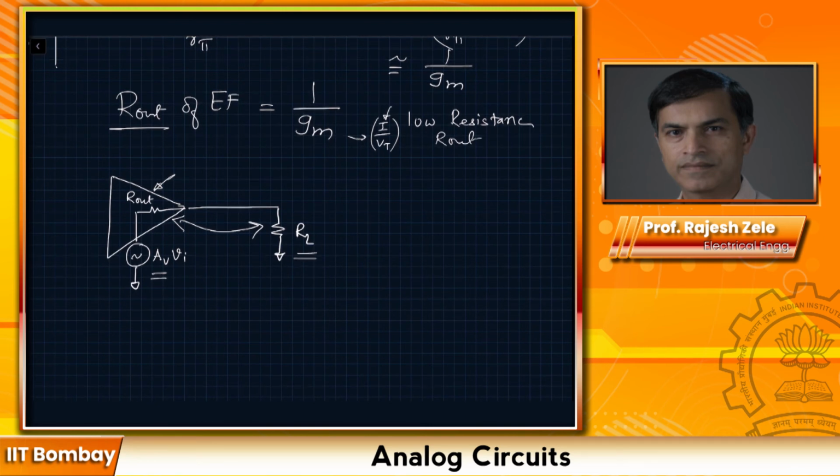In general, what you do then is you may have a chain of amplifiers amplifying the signal, and the last amplifier needs to deliver your signal to, let's say, a small resistance. For example, in the previous case, we had explained if I am driving a speaker. So the speaker has an 8 ohm resistance or something like that.